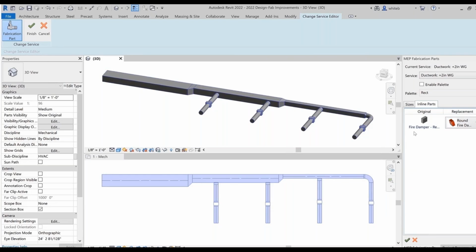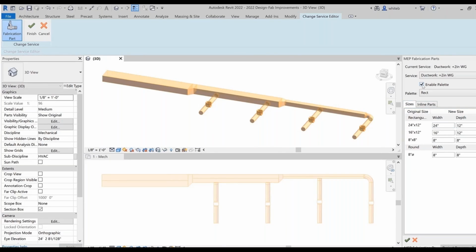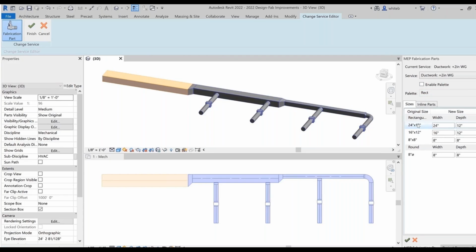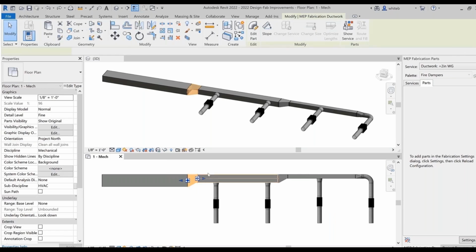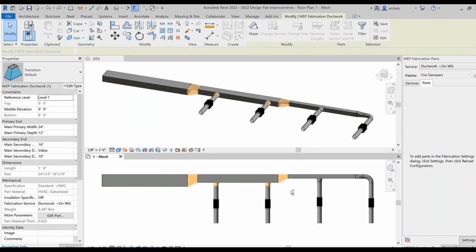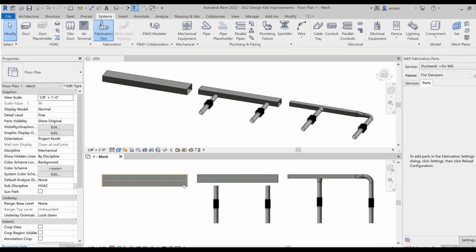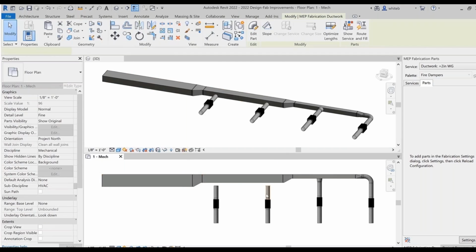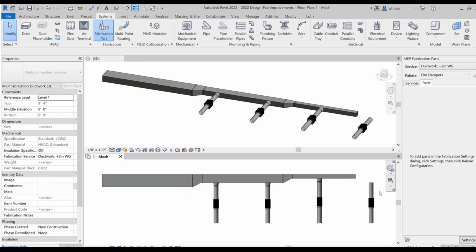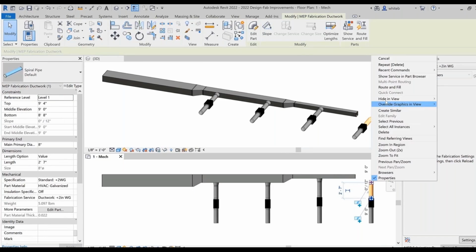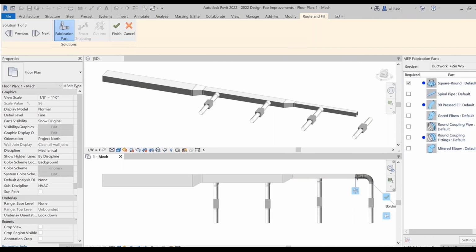These tools have been optimized to support our branch offsetting, our justifications, and equipment mapping without the dependency of our design lines. The quick connect lets you fill the gaps between a fitting and a straight section. And we're allowed to drag end connectors to straight sections to autofill the connections regardless of the size. And finally, I think my favorite one here, the route fill tool allows us to use added parts between 2 connected openings, giving us 1 or more options for our solution.